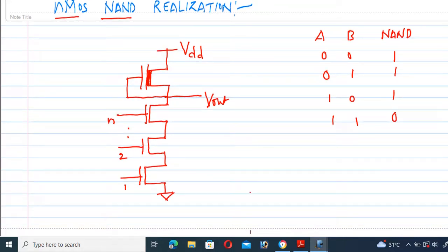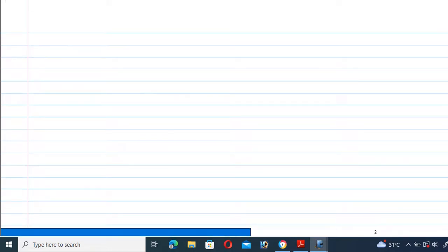We know that if we want an NMOS transistor to work as an inverter, it must satisfy the 4:1 ratio of the corresponding resistances. Each and every NMOS transistor is also called a resistance. From this diagram, the pull-up device, that is the depletion NMOS transistor, as well as the enhancement NMOS transistors also act as resistors. So the resistances can be represented in the form of impedances like this.